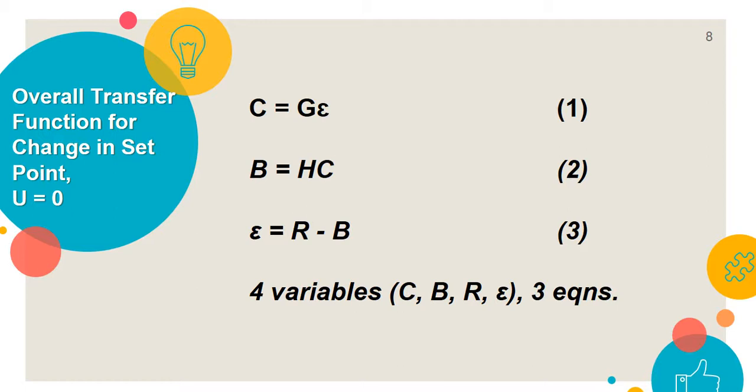This one came from the comparator. This came from, not from the comparator. This one came from the comparator. This is your set point, and what you subtract from it is the sensed value coming from your measuring device or your sensing device. That's your error.